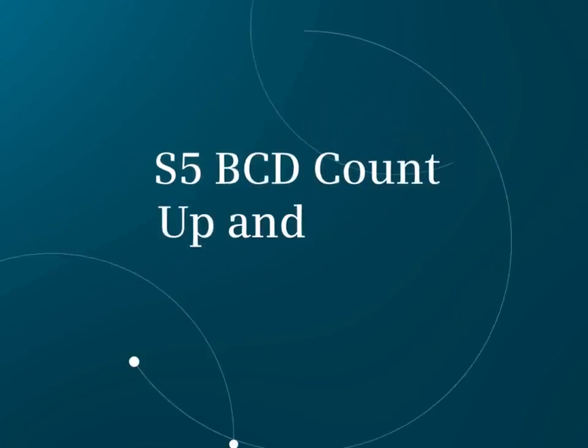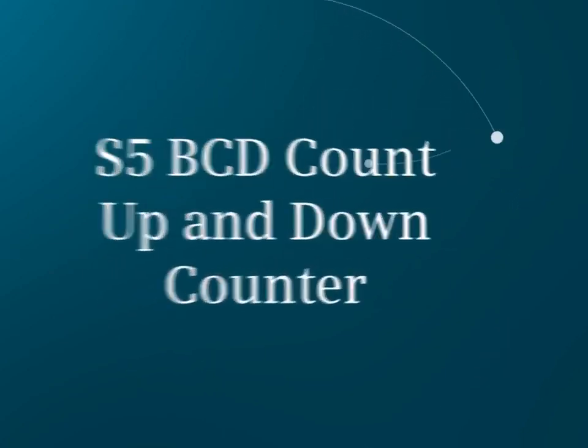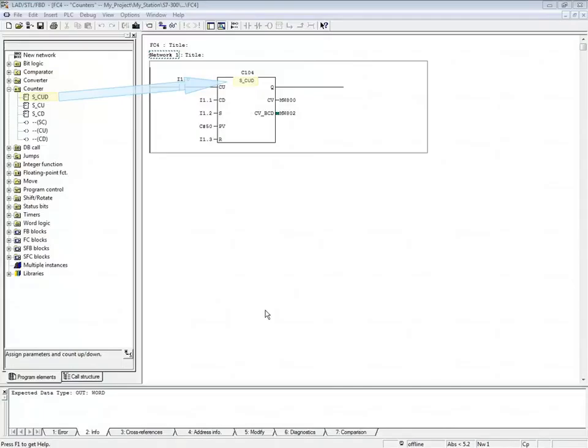In this video, you'll see the S7 BCD count up and down counter. For this counter, each time the CU input, I1.0, transitions from 0 to 1, the counter will count up. When the CD input, I1.1, transitions from 0 to 1, the counter will count down as long as the output